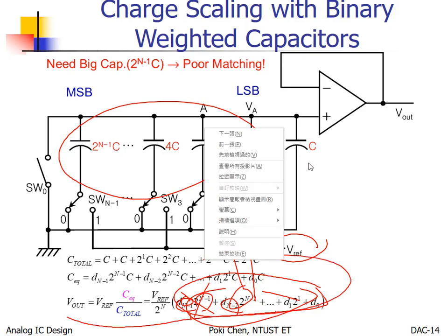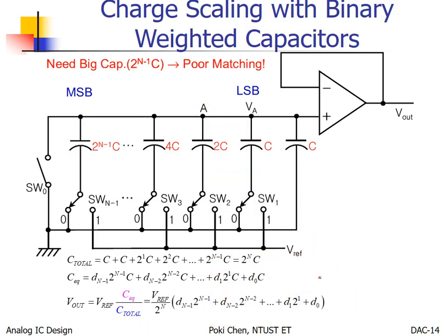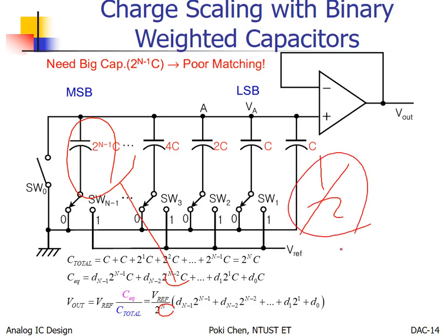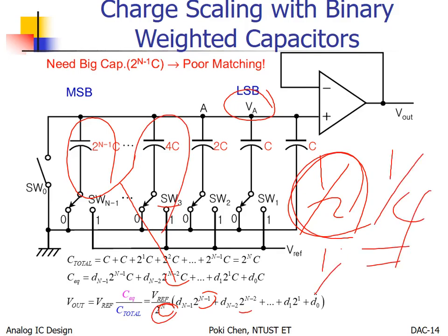And according to 2 to n's power configurations, you can see the first one dominates 50% of all the voltage here. Right? Because it is 2 to n minus 1 power, okay, divided by 2 to nth power, so it gets this one. And how about the second one? Here. So it got this, and all the way. So this is MSB all the way to LSB. Congratulations.